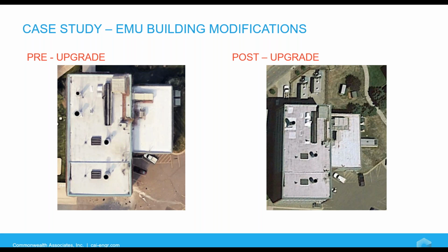But boiler 3 stack was demolished and the roof was repaired in that location. And the existing CTG exhaust was also relocated, with that roof location also being repaired. Interesting point here is the modifications to the roof actually voided the 30-year warranty on the roof, which had only been completed a few years earlier. So while the roof penetrations may seem minor, the modifications released the previous roofer from their obligations and forced Eastern to take on a little risk if issues arise in the future.